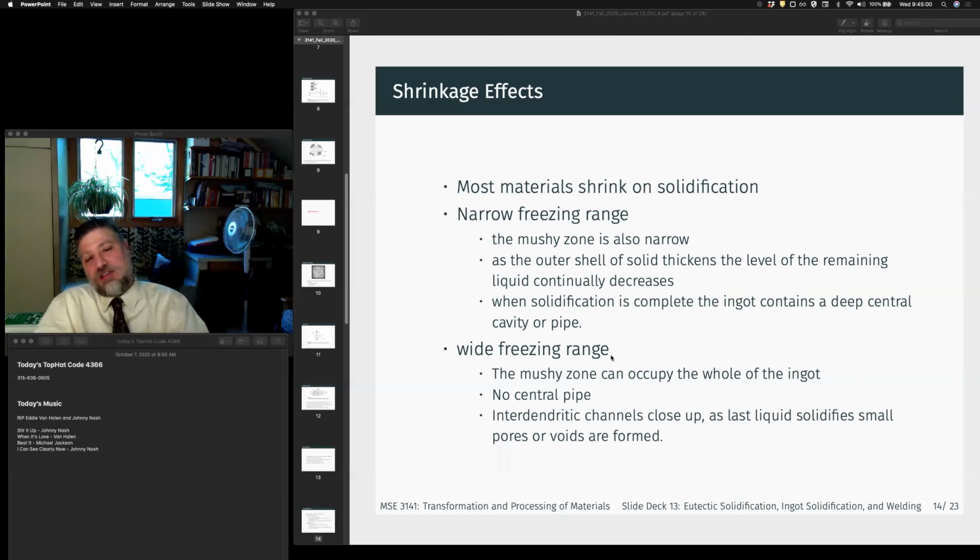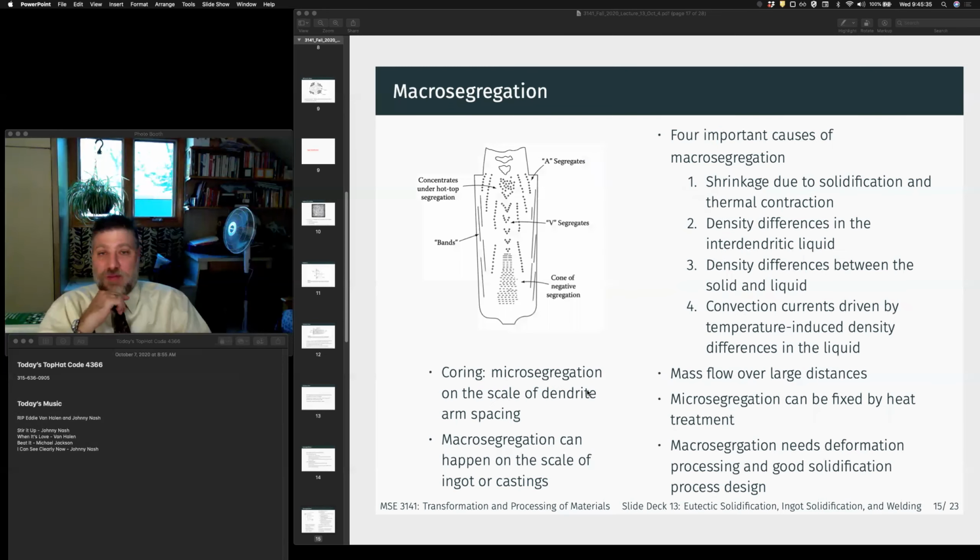And that also means additive manufacturing, right? Laser powder bed fusion, and 3D printing of metal structures. The whole thing is full of defects. It's full of voids. It's a huge mess. So they have to go through a process of hipping or hot isostatic pressing to try and close up a lot of these pores or voids, right? So there's lots of different ways to do it. None of them get rid of everything completely, right?